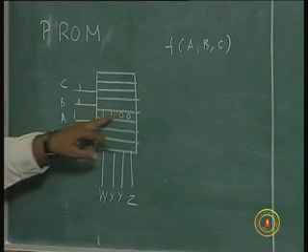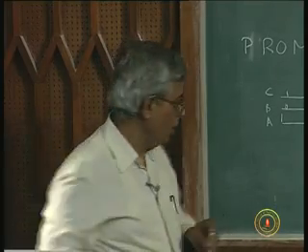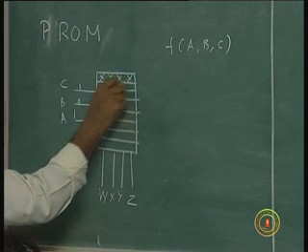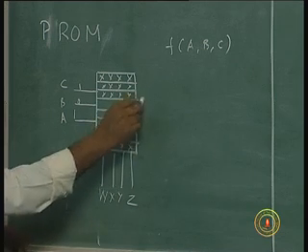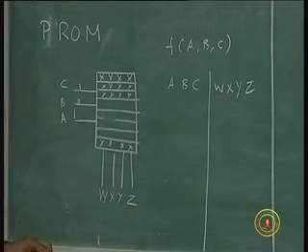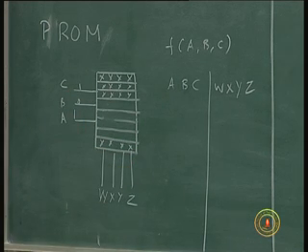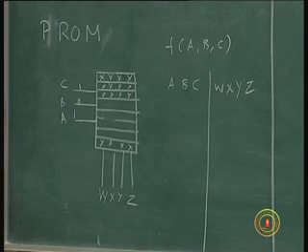So, introduce this programmability here. I will write as required in my truth table every time the new value, that is the programming aspect of it. So, instead of fixing 1100, I will have these 4 Xs which will be written and changed to my requirement. So, I will now get a new truth table for the given application. In that truth table, for each of the combinations, what is the value of W X Y Z, and those values of W X Y Z I should put in this position for 0 0 0 input, 0 0 1 input here. That method, that procedure of putting the different values of W X Y Z for different input combinations is called programming.